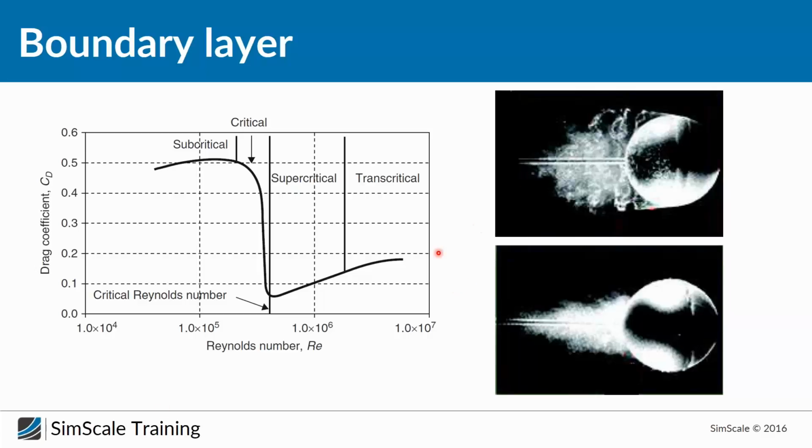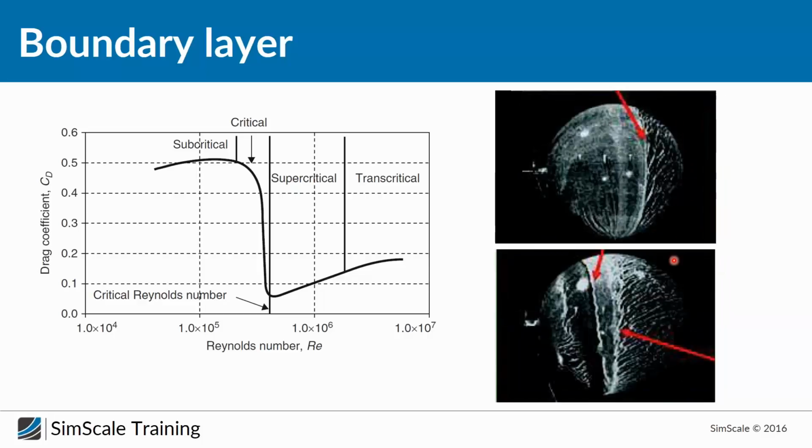And just to underline this argument, here you can also see the surface flow. This is from wind tunnel measurement, and here it was visualized using oil on the surface. So the air is coming again from the right, and you can see here we have the flow separation starting very early, which you can see because basically here the wall shear stress is changing its direction.